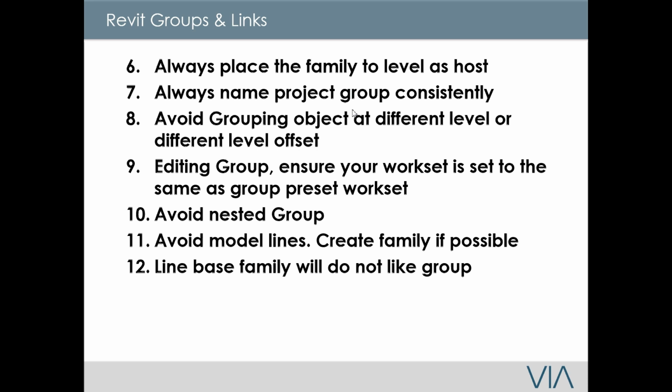Number 12, if you built your families as line-based, do not put them in a group, because it will always break. It would always want to be placed outside of the group. So regardless of what you do, if you're trying to place it inside a group, every time you edit, it will want to make a copy of itself. So be aware of that.